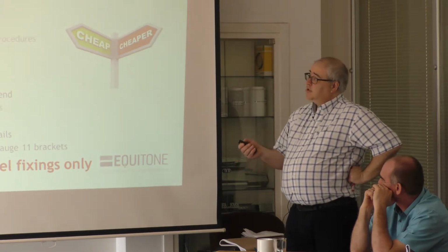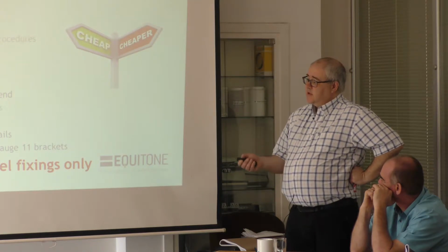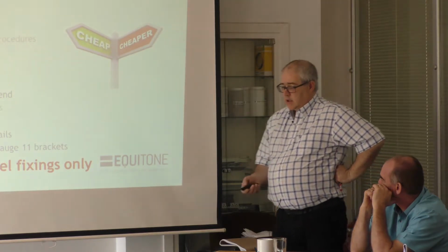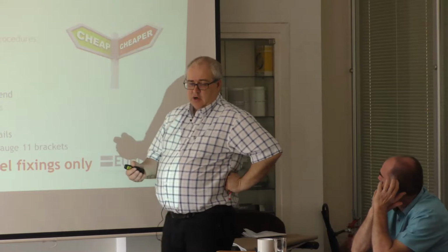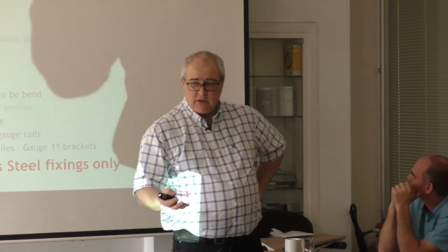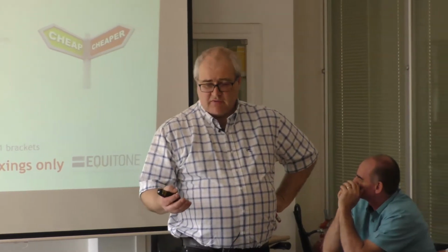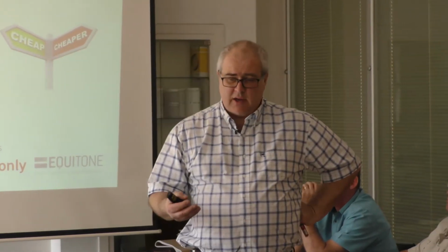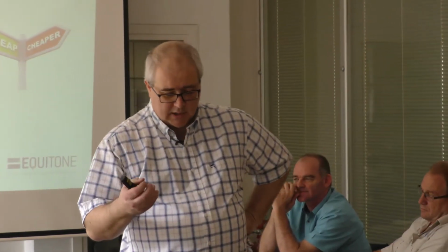Now, when you're using this galvanized system, even in the thinner gauges, the metal is much harder and tougher. You're going to get harder wearing on your drill bits. You're going to have to use the stainless steel rivets, which are a little bit harder, they need a little bit more force, so there's more wear and tear on your rivet guns. Your batteries won't last as long when you're working with galvanized steel compared to the softer aluminium.